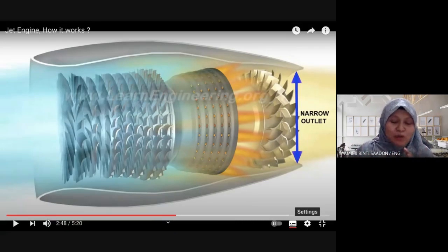All the energy that we mentioned here, pressure energy, kinetic energy, temperature, pressure, it links with the fluid, the air in the engine, okay? Not the rotation of the turbine, okay? When we say kinetic energy, it is not the kinetic energy of the turbine rotation, that is another story. Kinetic energy is the kinetic energy of the fluid. That's why we learn aerothermal, so aero, the fluid.